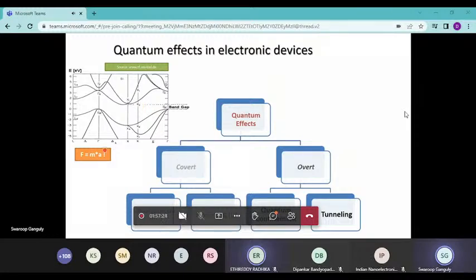And once we extract this effective mass, after that, instead of solving the Schrodinger equation of quantum mechanics, it is okay to solve simply Newton's laws, but instead of the usual mass, just use m star, the effective mass, and all the quantum mechanics gets hidden behind it. Similarly, scattering of electrons as they move inside the crystal to give you a finite resistivity and resistance is also a quantum mechanical effect. But once you have calculated the mobility, you can pretend it's a classical quantity because all the quantum mechanics is hidden behind it, and you can do simple classical mechanics with the mobility.